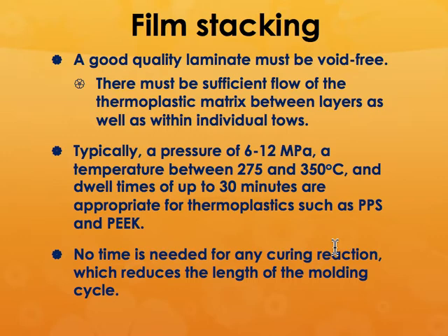But the other advantage with thermoplastic composites is that you can make these composite parts within a very, very short time. So typical manufacturing times are less than 10 minutes each. Compare that with the regular thermoset type of matrices, which can take you almost an entire day to make.